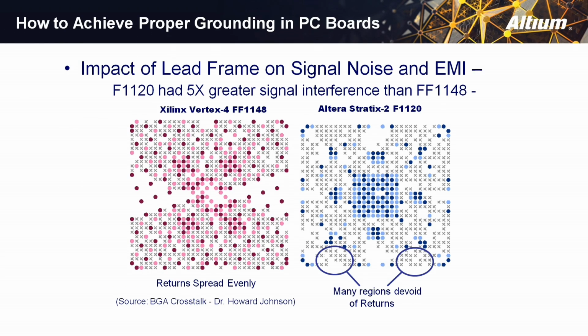The point, though, is from a signal integrity standpoint and from an EMI standpoint, it isn't just the circuit board that has to be designed right. It's the ICs that we put on the board. As the great Henry Ott once said, you can do a perfect job of circuit design and a perfect job of layout. And the moment you populate the board with ICs, all bets are off, because there are far too many poorly designed ICs in the world today.